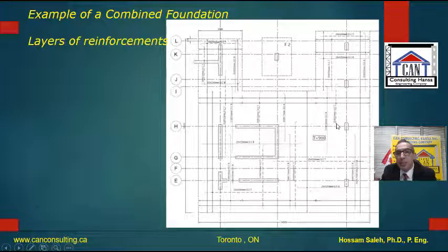Here is the top bar, and the top bar is a dotted line, and then you have another top bar with overlapping length, and here you have the dot, and that shows you this top bar will go from this part to this side, from this side to this side, okay, and this bar here has the dot, and it will go from here to here. So the top bars here can be dotted, and the lower bars, as you see, are solid bars.